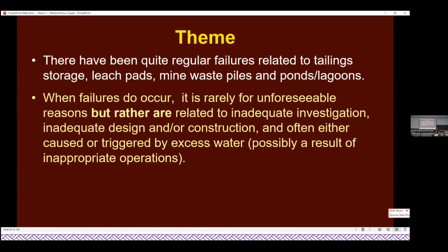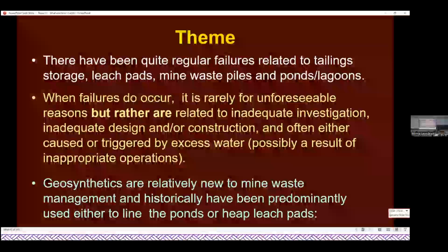And when those failures do occur, it's rarely for unforeseeable reasons, but rather related to inadequate investigation, inadequate design and or construction, and it's often caused or triggered by excess water, which can often be a result of inappropriate operations. Geosynthetics are relatively new to mine waste management and historically have been predominantly used either in ponds or heap leach pads.